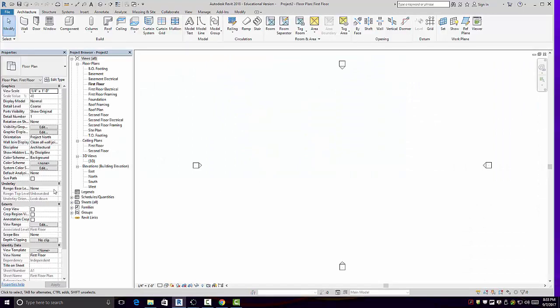We're going to start out with this. So let's talk about the horizontal. If you look at the floor plan, actually I have a more convenient floor plan for myself. The overall house is 34 feet by 28 feet, right? When we start out, usually we're still thinking plans. The definition of a floor plan is a horizontal section at 4 feet.